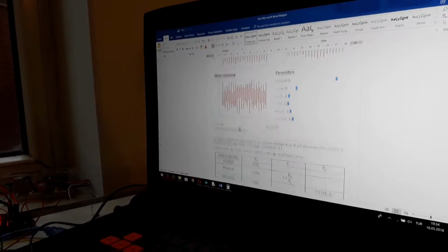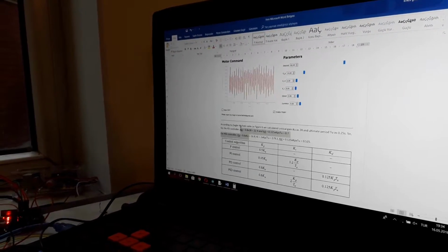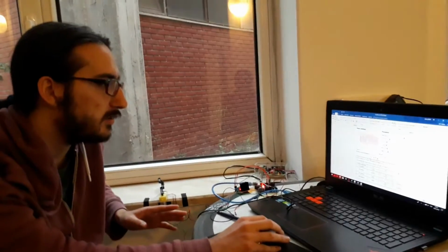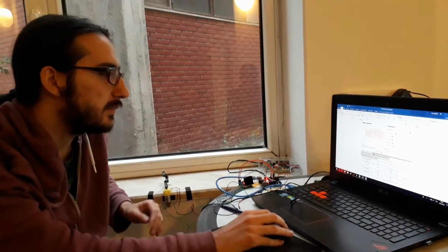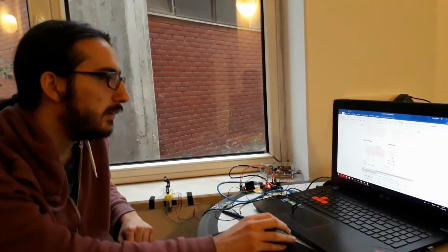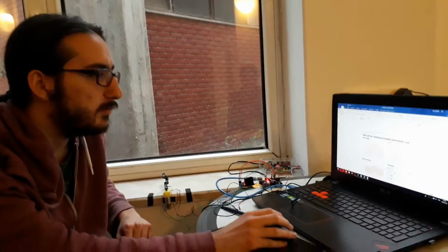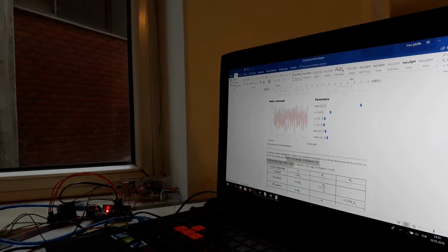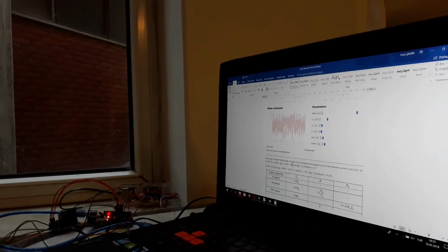This Ziegler method basically places zeros such that the root locus plot is crossed at points in which we want the system to cross. For example, for the Kp value at which the system is critically stable, using the Ziegler method and designing some PID controller, we can obtain a stable system such as underdamped. And this is the basic idea behind the Ziegler-Nichols controller.